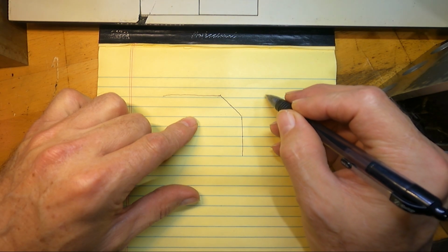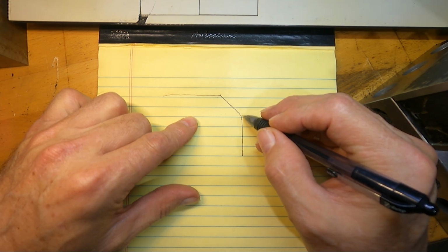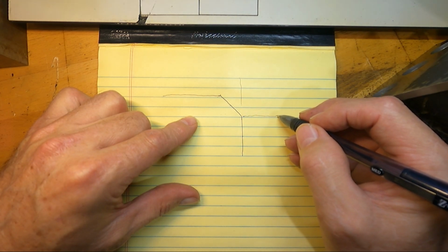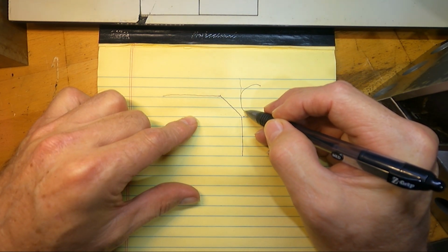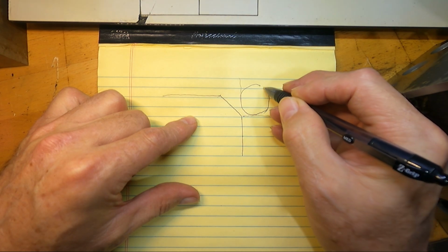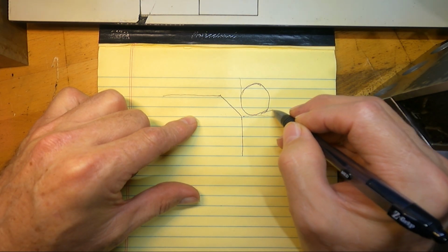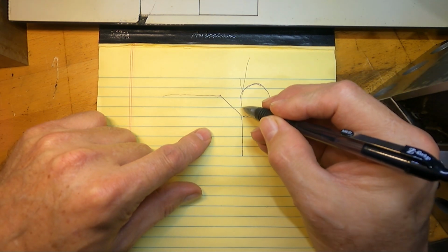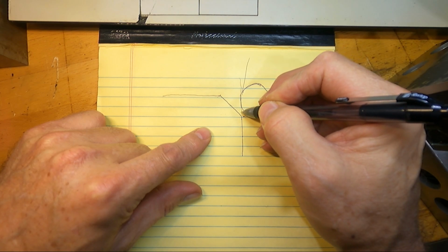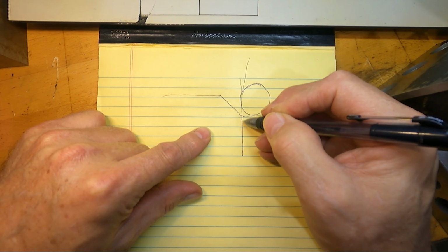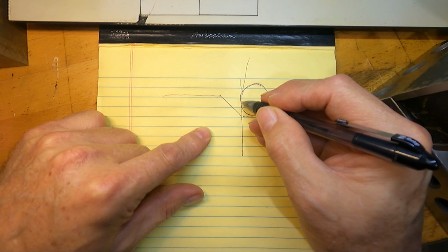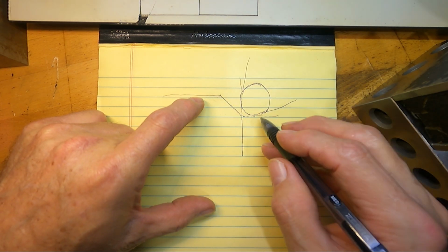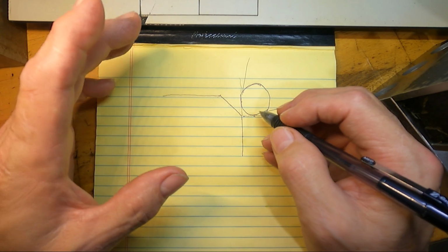Let me draw right here. I'll just kind of project this out. If we imagine this big tip radius right here of the tool, this could be any shaped tool you want. That's the tip radius of the insert. Now, when you touch a tool off, of course, you're going to take some kind of facing cut. You're going to set that Z0, and then you're going to take a cut down this OD and mic it, and you're going to set that X0 if you're doing it manually.